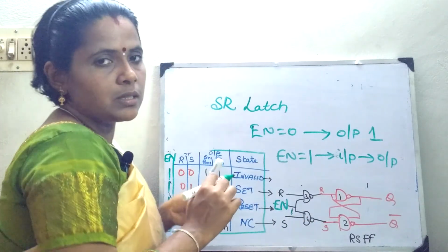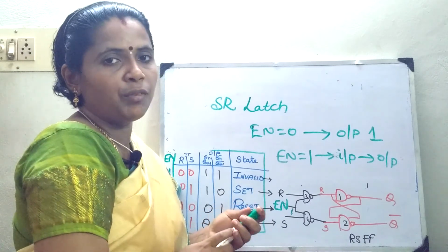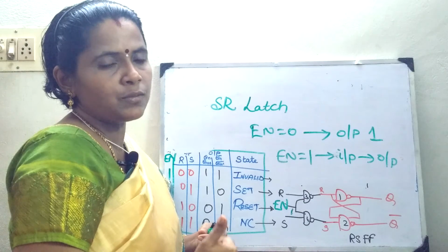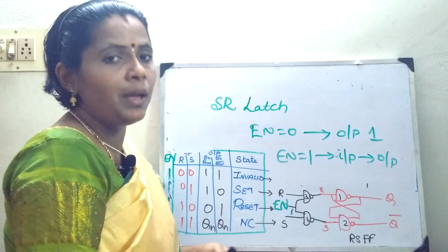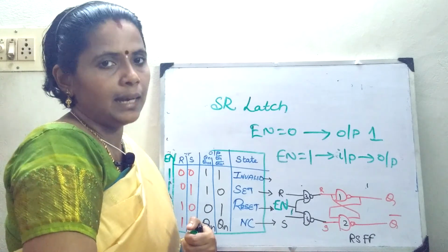Okay. So this is the concept today. We have seen how your RS flip-flop works with NAND gates, how you can convert it into a clocked RS flip-flop, that is an edge triggered flip-flop, and the same thing how you can convert into a gated SR latch.